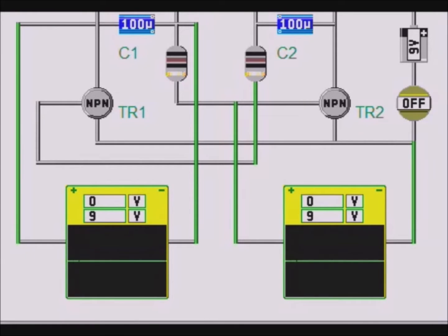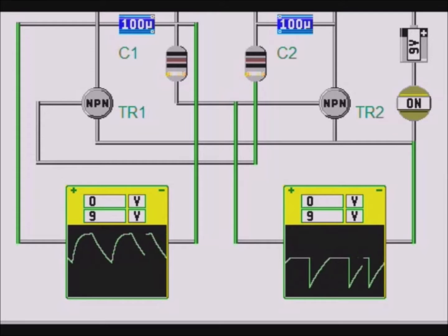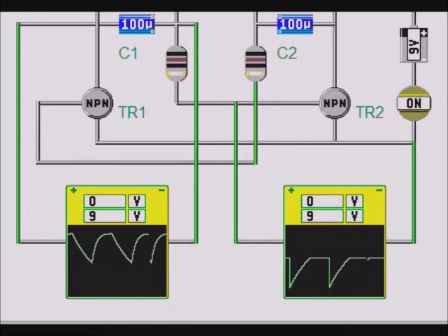We have placed two oscilloscopes to monitor key voltages. When we switch on, we see these distinctive curves. The first oscilloscope monitors capacitor C1. We see it charge to near full capacitance before TR2 turns off. Then it discharges before repeating the process when TR2 turns on again.